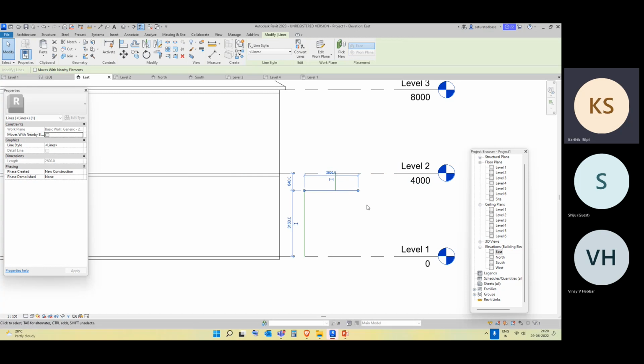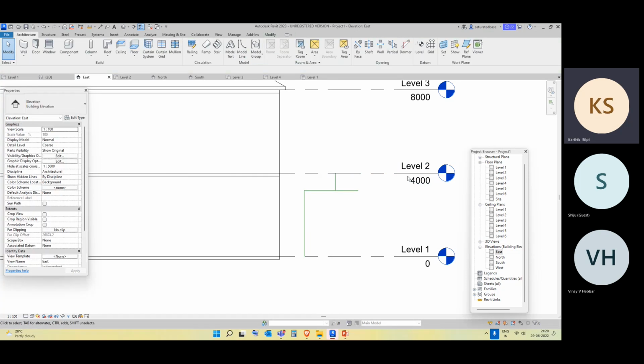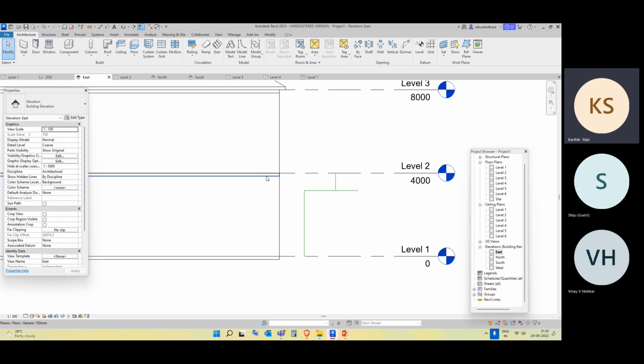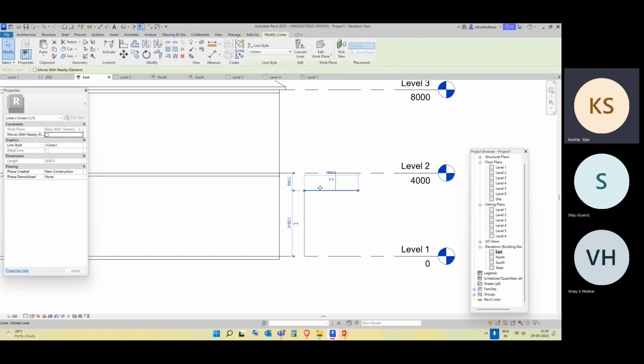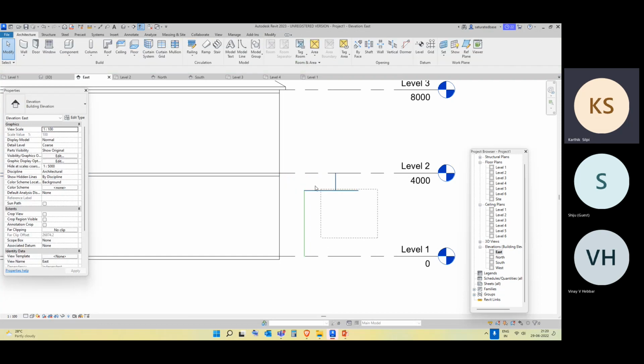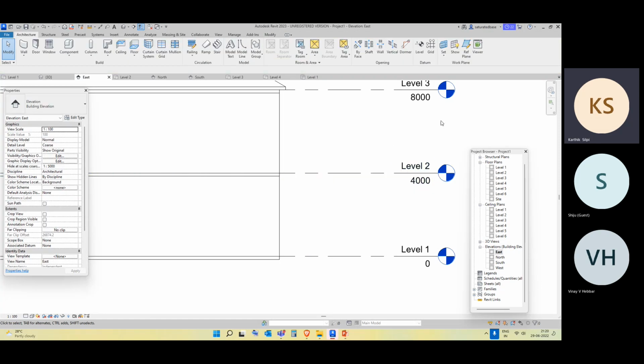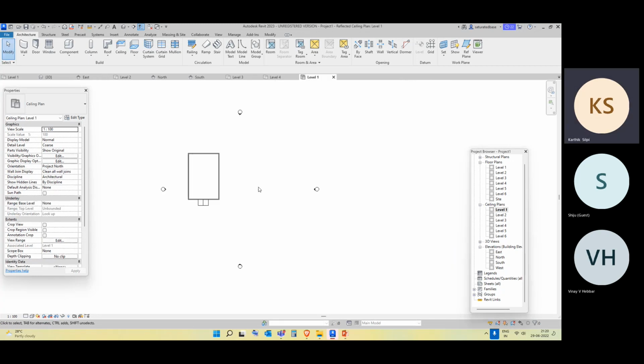In this area, we are going to see pipes for heating or ventilation, and also ducts, and also fire protection pipes, and also various electrical cables that will be running between these places, because this is what the ceiling will look like. Whenever we enter a building, we are not going to see this ceiling. We are only going to see this ceiling. This is the working place between this level and this level. This is a working place for all the MEP professionals. All their connections are going to pass. So one thing you have to be mindful is what is the distance we are going to give for them to work.